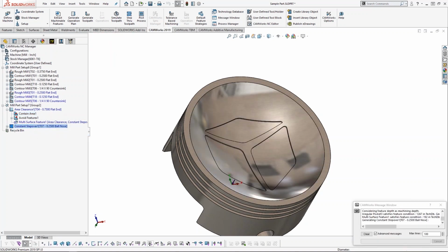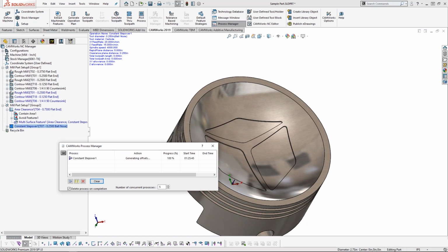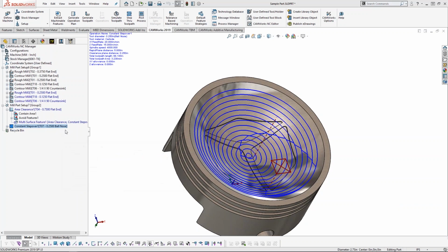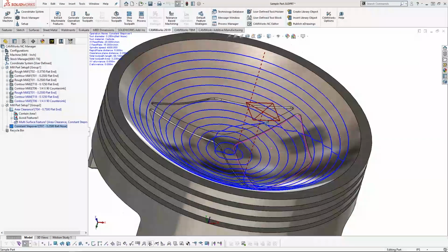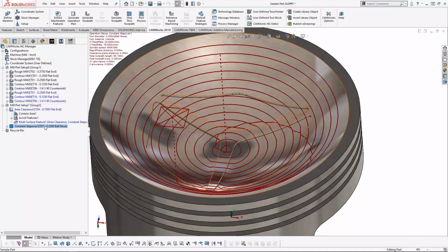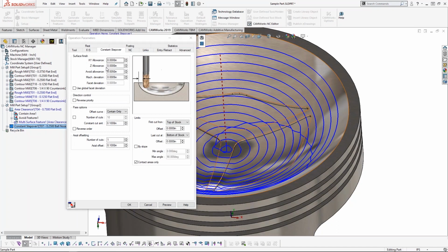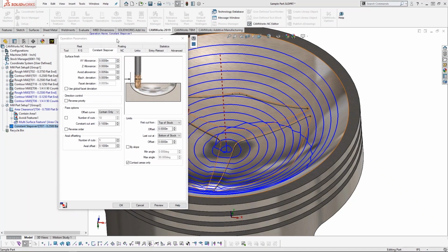Let's generate some toolpath for this finish pass. I haven't adjusted any step over or depths of cut or anything, so we'll take a look and see what it gives us. Okay, so we can see it's sort of dipping down into the logo. And if we adjust the step over here, this is considered a constant step over, 3-axis toolpath. It's intended to create an equal scallop in all directions. So if I adjust my cut amount, just cut it in half here.